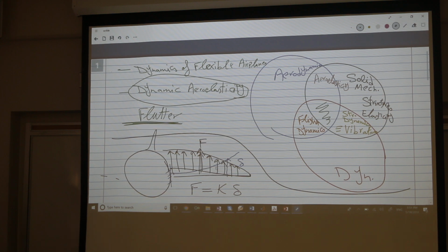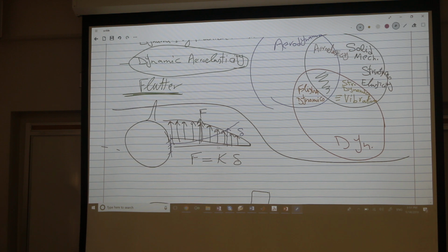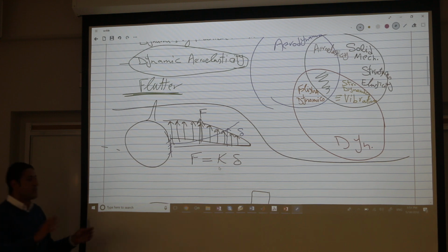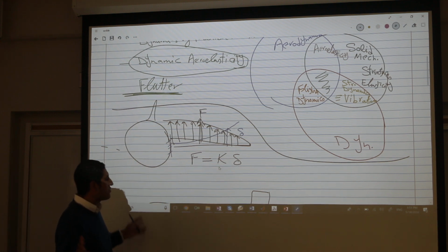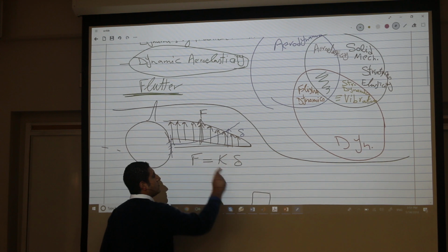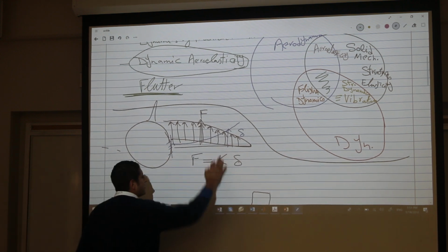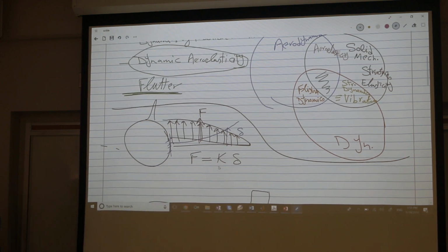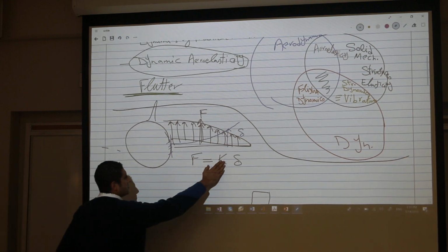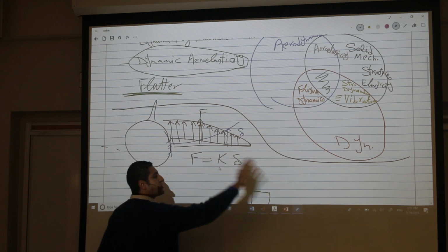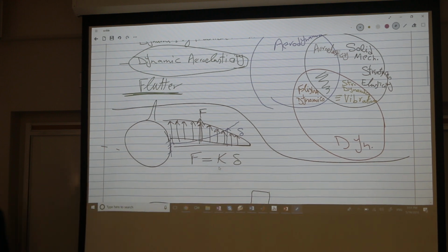And as you can see here, no matter how complicated your model is, in the small deflection region the relation is linear, and whatever theory you're going to use, Euler-Bernoulli or whatever, it will just give you a value of this constant. So to me, at the end of the day, it's a spring with some constant. And the structural theory will give you the value of this constant depending on the geometry and rigidity of the beam. This is not my concern.